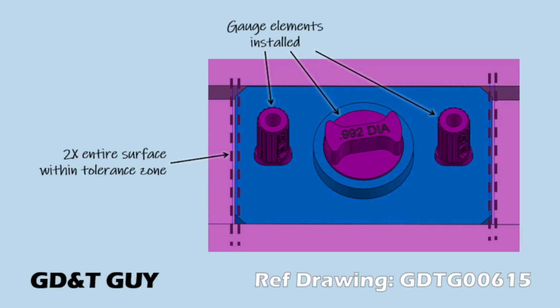a fixture to be used with a CMM, which is how you would probably have to approach these ends. I was even thinking for a minute that maybe you could somehow mark the datum A simulator with 2 sets of lines representing these tolerance zones, and then you would visually confirm the profile. Maybe. But if we're talking CMM, maybe a much simpler fixture could be reasonable, without the special gauge elements, just the datum A and datum B simulators. There might be a way to build something like that with setup blocks.